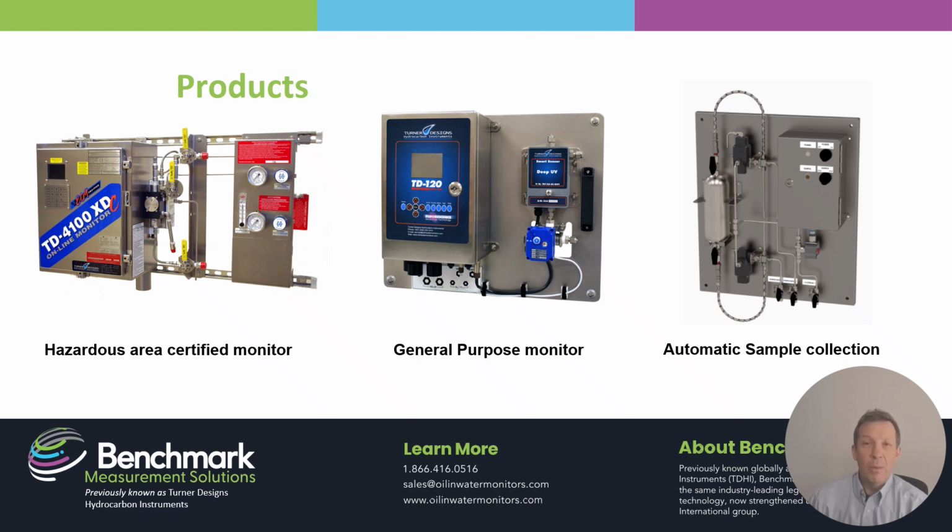When an operator wants to know the type of hydrocarbons that are in the water, a sample thief can be used in conjunction with these two monitors. This will automatically collect a water sample when an oil alarm is actuated. Operators can collect the water sample, take it to a laboratory where it can be analyzed for the type of hydrocarbon to help identify the leak source.